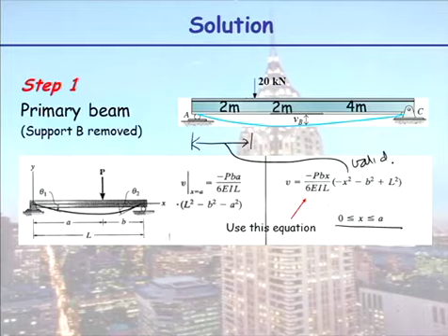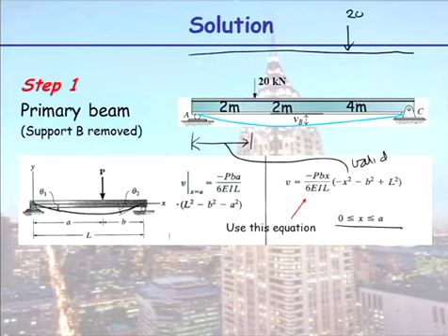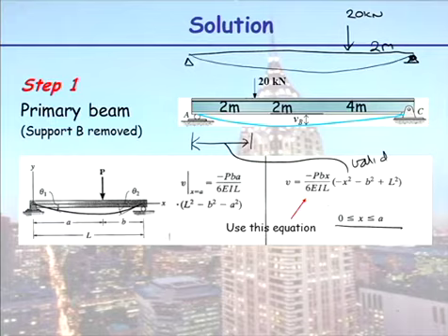But in saying that, how about I just rotate? We want this deflection over here. It's not within the range we want it to be, is it? So why don't I just rotate my beam on a vertical axis? So I'm just going to turn it round here. That's my 20 kilonewton here. That's at 2 metres. There's a support here. There's a support here. There's my deflected shape. We want to know the deflection here, VB.